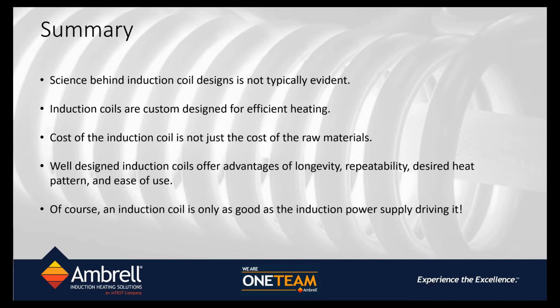All right, thank you, Girish. Our next question is about coil design and load matching. How the number of turns affects the frequency and the inductance. So typically, the larger the number of turns, the frequency goes down, because the inductance of the coil is much higher. The larger the number of turns, if it can be fitted around the part, lends to a more efficient process.